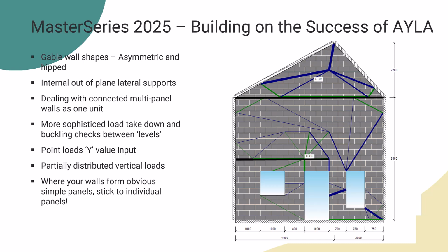And this actually then does create two domains in the wall in terms of yield line analysis. So this is a completely separate yield line analysis to this whole domain here, with its restraint coming in part way. If this were all the way across, then we would have three domains of yield line analysis.